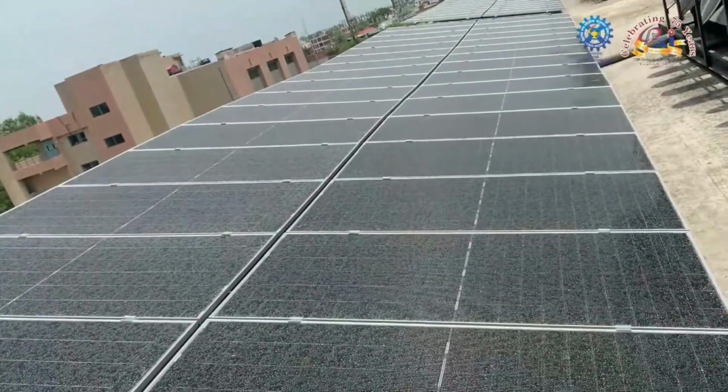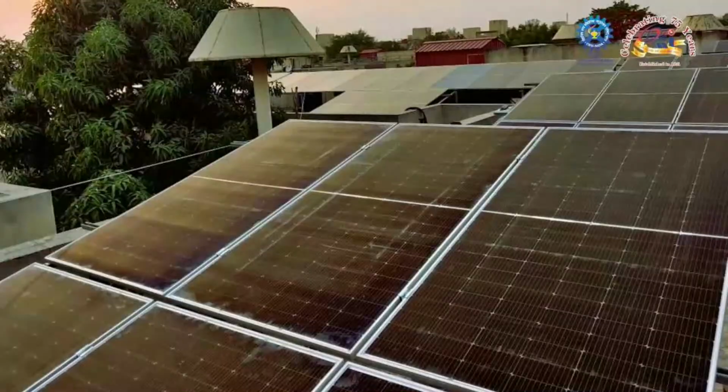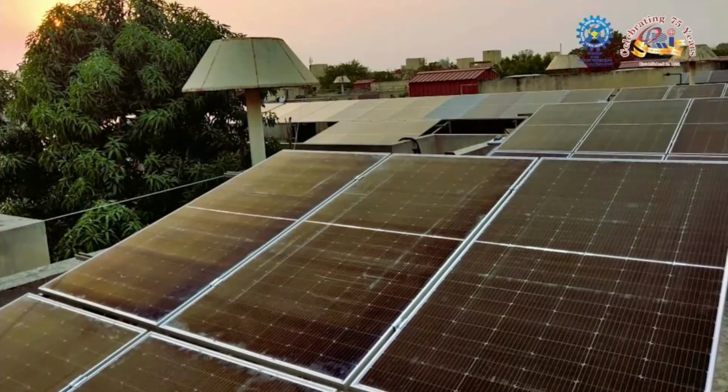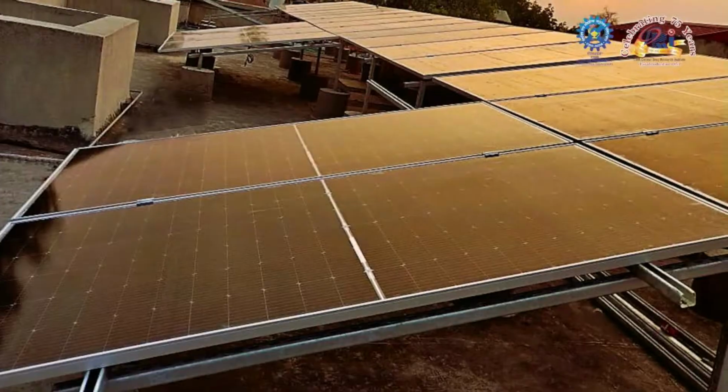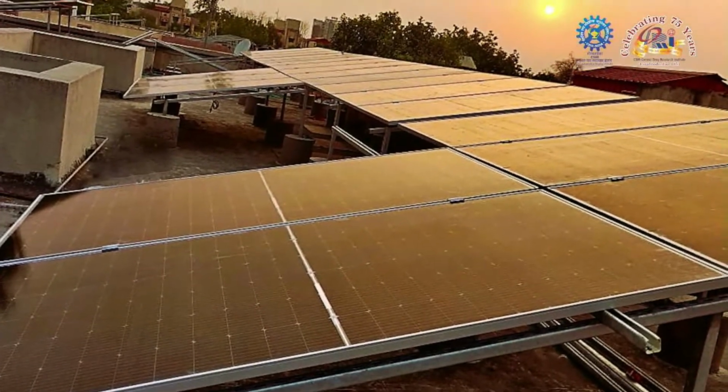Solar panels at CSIR-CDRI now cover 100% of the rooftops of the R&D building. In phase 2, we will aim to cover 100% of the rooftops across residences and administrative buildings. Our current demand for electricity is around 3 megawatt, whereas the peak generation by the solar plant will be around 1 megawatt. Factoring in the shorter winter days and occasional inclement weather, our rooftop solar plant will meet close to 30% of our requirement. Biomedical research facilities need to plan for the future.